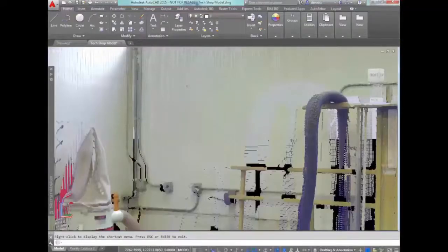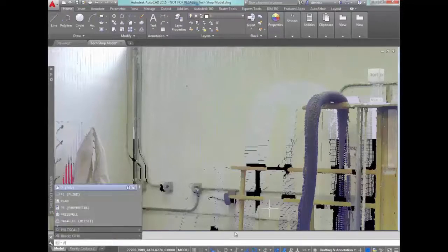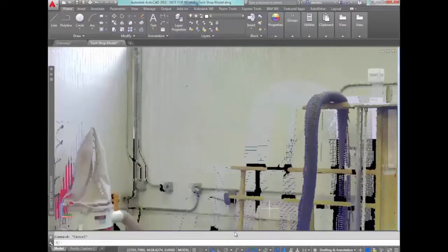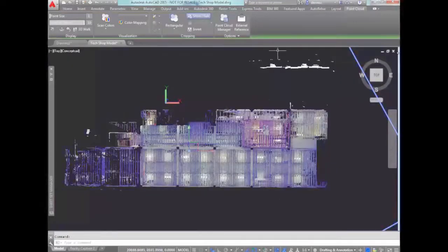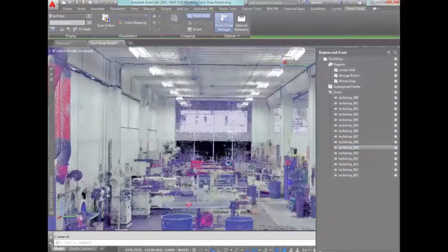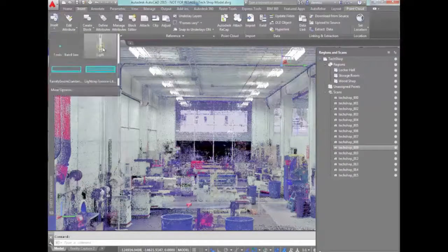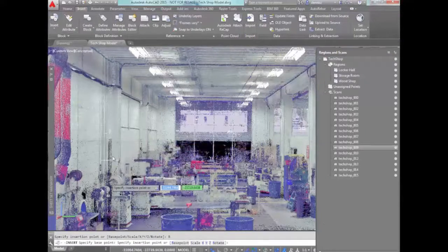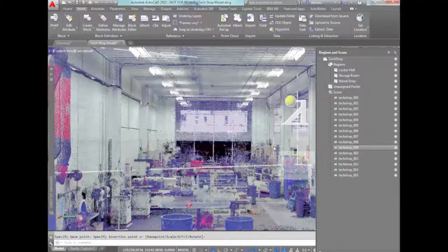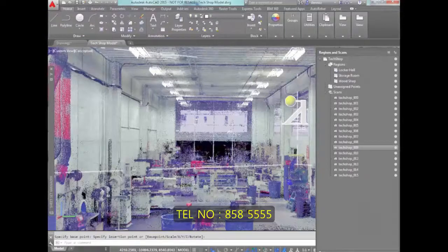We can include some objects. For example, we can input objects here. I'll go back to the original plan. For example, I'll go inside one room. For now, I'll be choosing room 9. So what am I going to do? I'll insert one object. Click on insert, light, click on the base point, insert the object. Okay, this is the object. Then I'll try to put it here. And you can now view the output if you want to put some lights on this side.